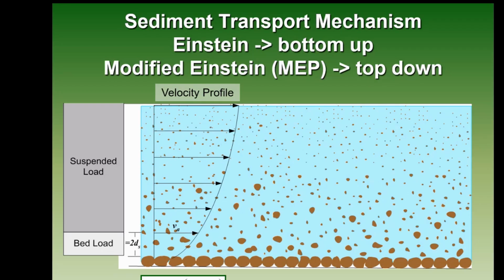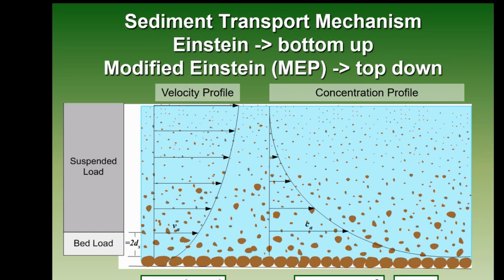So the idea: we have a velocity profile, the log law, we'll get a concentration profile, the Rouse law, and if you multiply those two, you get a power form times a log, and that's mathematically intractable, meaning you don't get an analytical solution from the power times the log. Maybe 10, 20, 100 years from now, there'll be a way to do that, but to this day, there is not. So we can still solve them numerically.